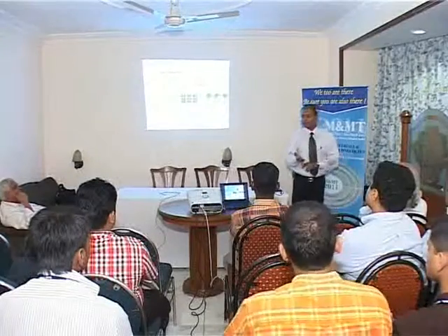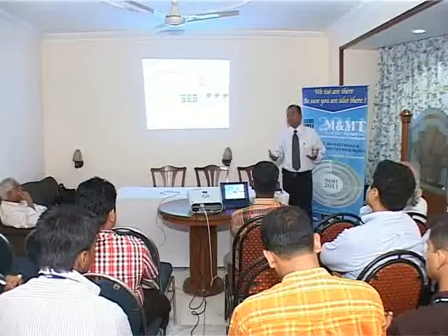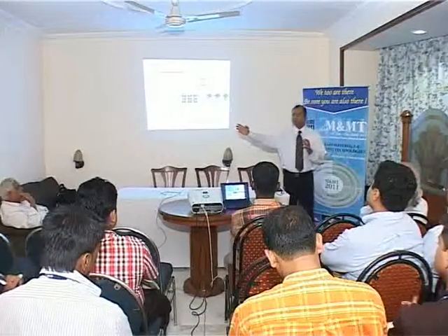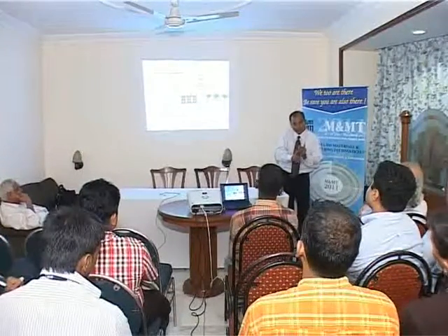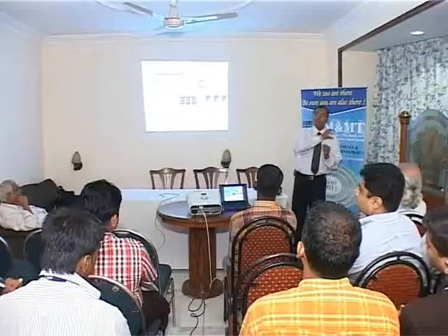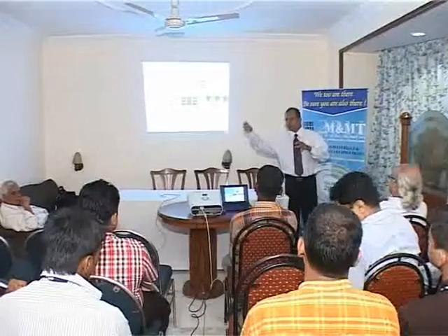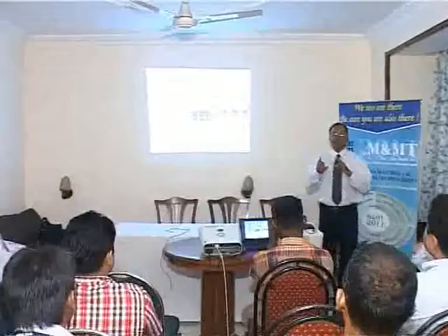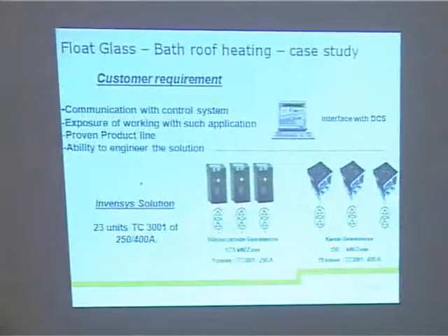I mean, you talk of elements like silicon carbide or molybdenum disilicide or tungsten, these all have different thermal characteristics, and unless you are doing proper power management of it, you will actually blow off those elements, and those are expensive ones. So what we are talking about here is, what is the technology available today and where are we going towards? See, many people were using only an on-off controller, and then they were using only a power contactor and doing the on-off, on-off, on-off. Now doing that on-off was giving a thermal shock to the heating elements, reducing the life, and giving thermal shock to the insulation, so reducing the life of the insulation as well. By making use of a power controller, you are giving a gradual power control.